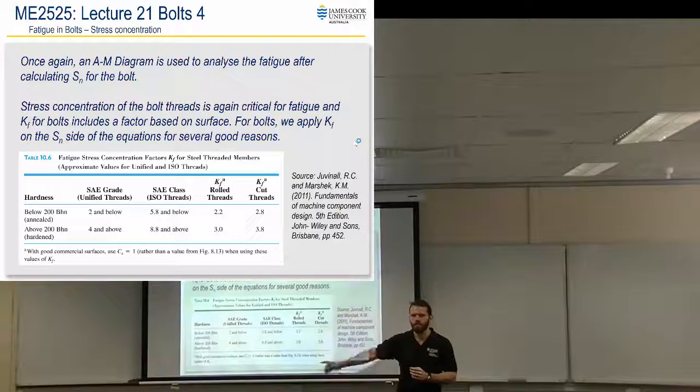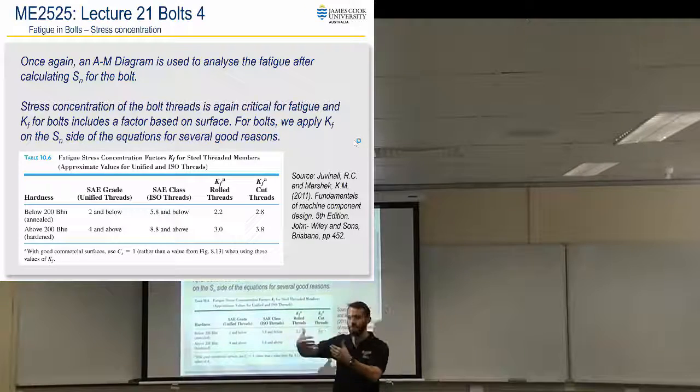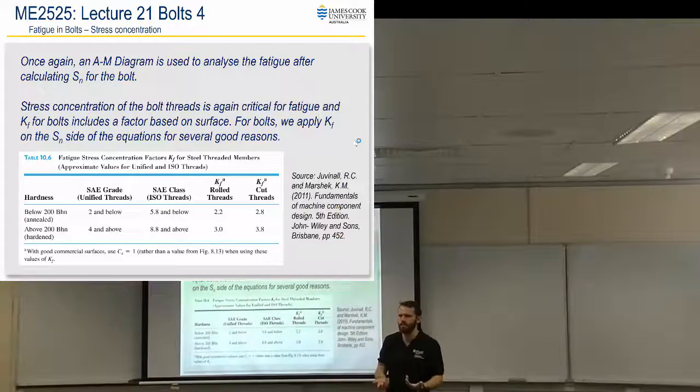What happens to stress concentration in static loading? Remembering that initial tension is static loading. If I had a stress concentration of, let's say, 3, and I statically load something, we have that localized yielding in the stress concentration zone, but the rest of the cross-section hasn't yielded, and as far as static failure is concerned, we're still okay. And that's why we didn't really use stress concentration in static analysis of the bolts, because stress concentration isn't critical for ductile material for all the reasons that I told you when we were initially talking about stress concentration. Alright, so theoretically, it would yield locally at that initial tension point, but the rest of the bolt wouldn't have an issue. Now, if you're talking about fatigue, stress concentration is very, very important.